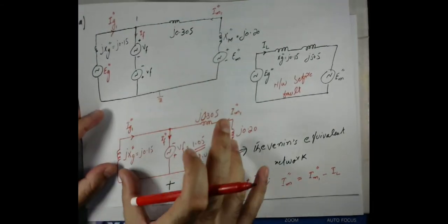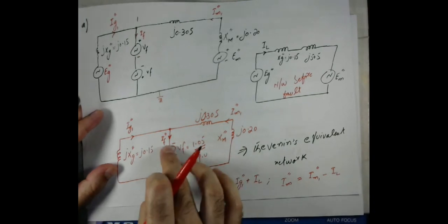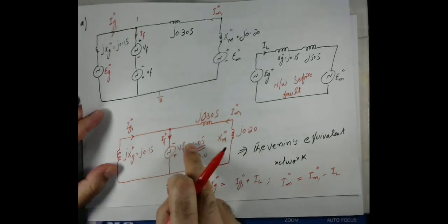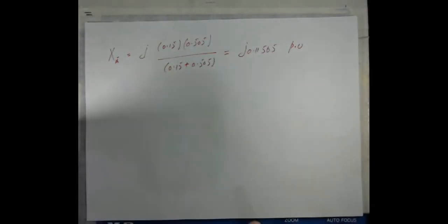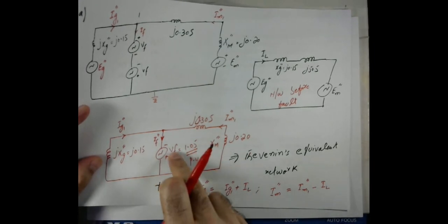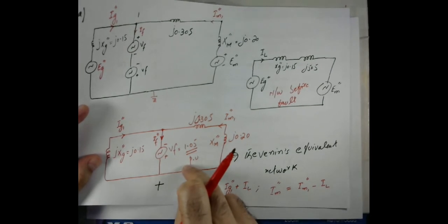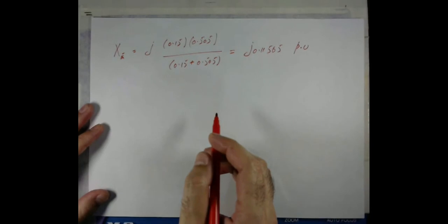So this is the Thevenin equivalent reactance. Now, because we have calculated the equivalent reactance of these two branches, we simply divide the voltage by the reactance to get the current. We know that the voltage at the fault is 1.0 per unit, as we make this assumption.